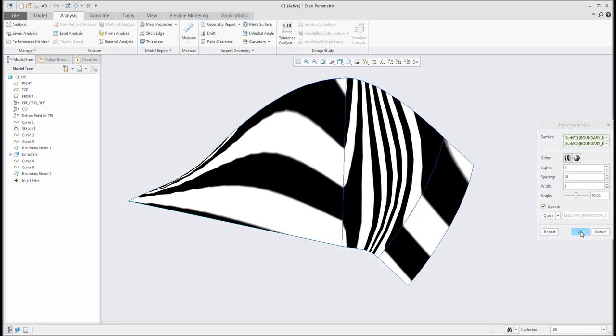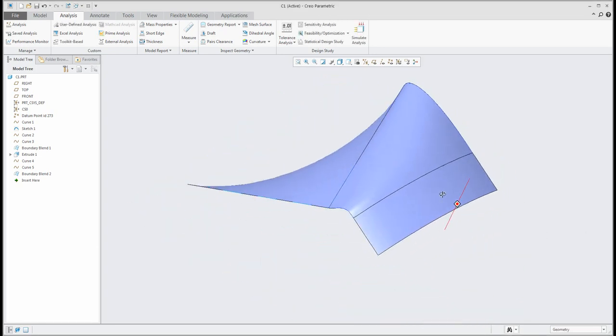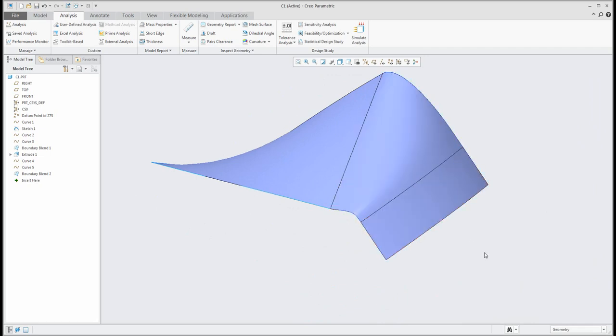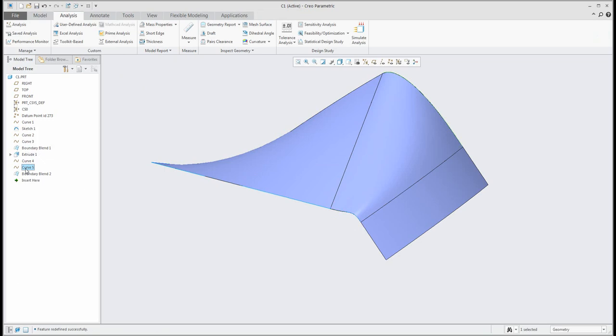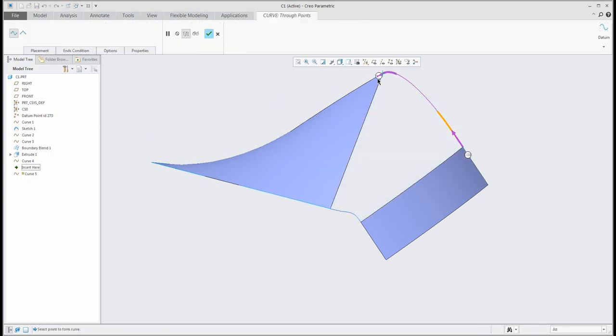It's the same as how designers create cars, and if you have a look at the cars, you can see that the connected surfaces are really smooth. So if you would like to repair this tangency, you have to go back in the model tree, select specification and select the curvature on that curve, go back, and on the other one select the curvature here.